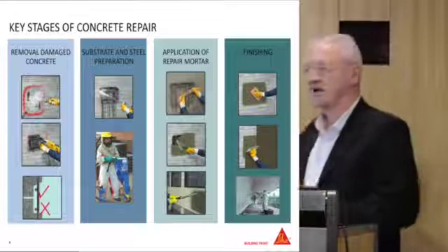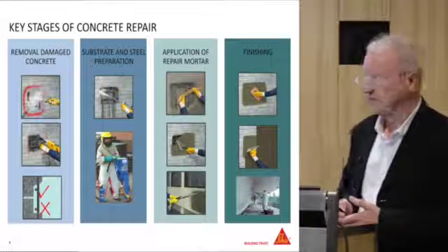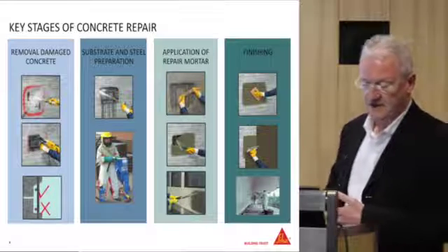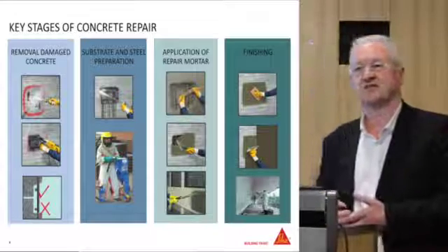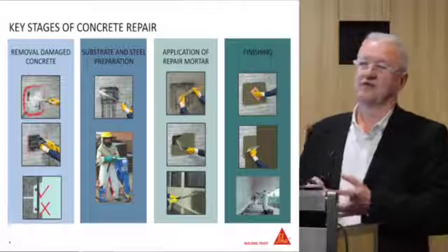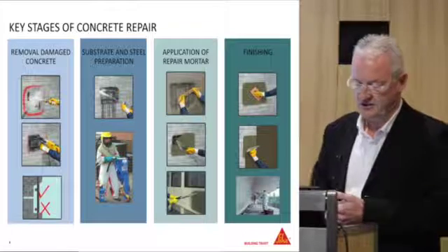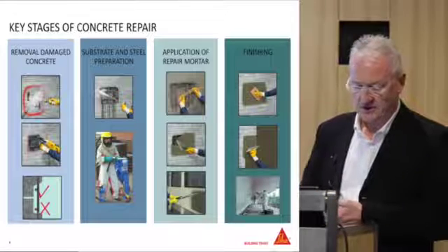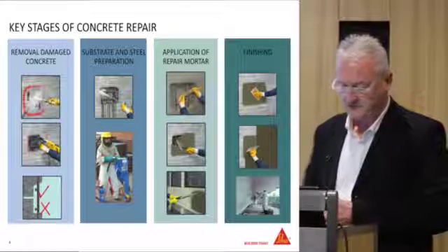So the key stages of a concrete repair are, first of all, to identify the areas which need repairing, and then to break out the concrete. That could be with small jackhammers, CP9s as contractors use, or we can actually use hydro demolition again as well.